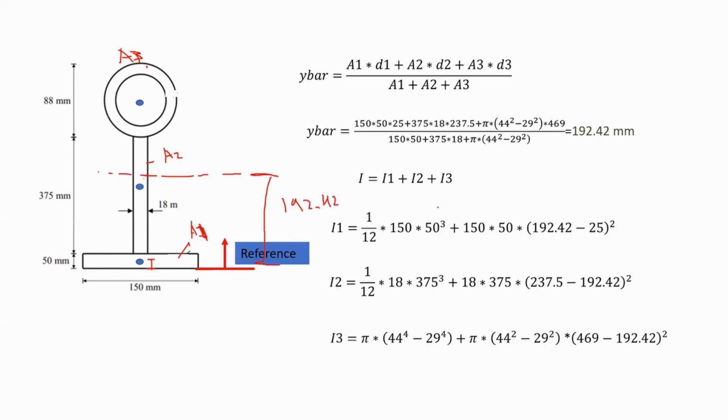In here we have calculated the moment of inertia for the first part, number 1; number 2, the other rectangular part; and lastly, for the hollow section, number 3. And notice I considered the parallel axis theorem, because the centroid of each part is far away by a specific distance. For instance, if we consider this part has its centroid over here, let's see what the distance is.